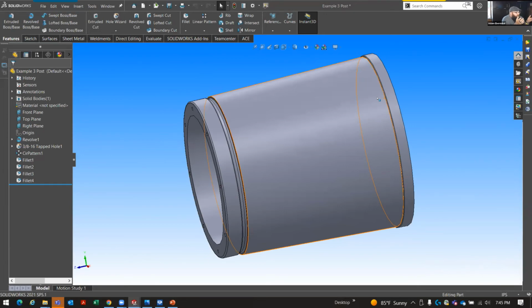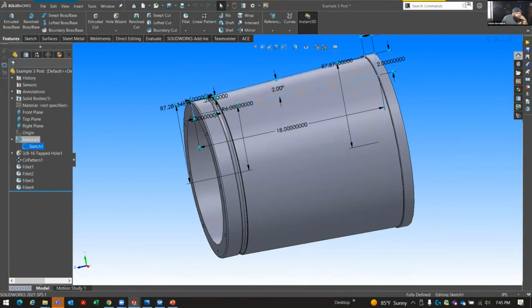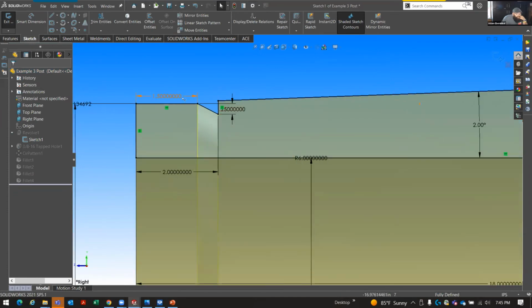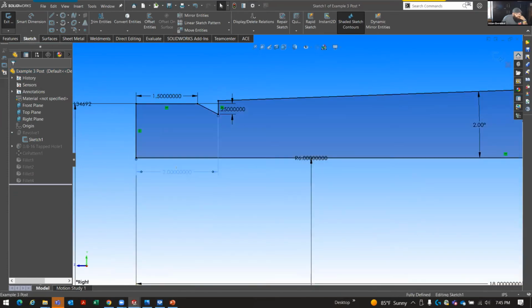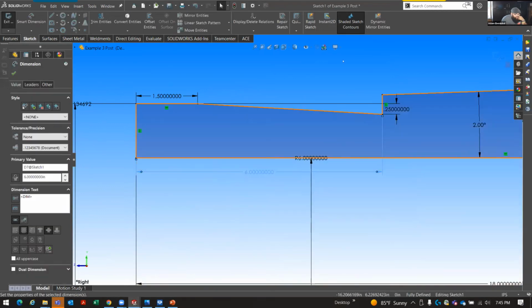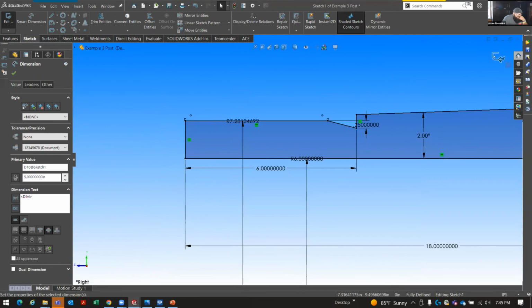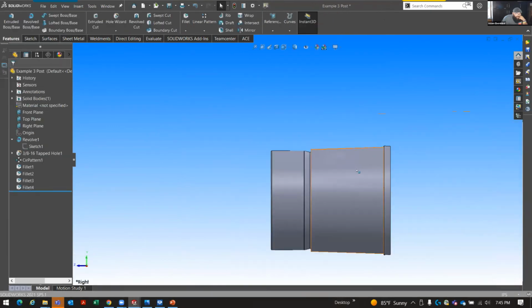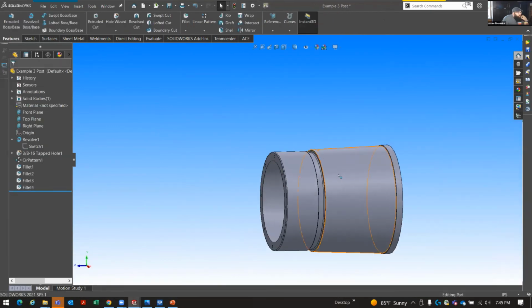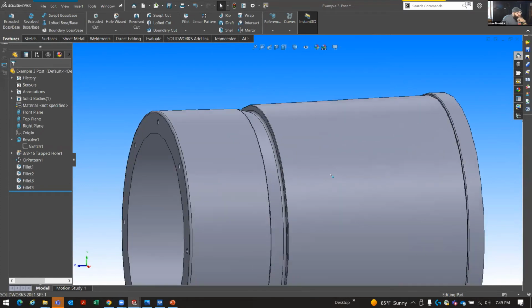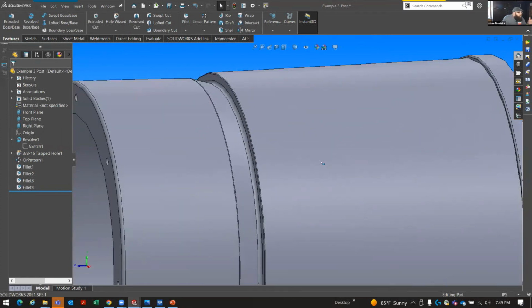Yes, which is only about 3-4 inches, right? Yeah, in theory. So I could have gone back in and changed this dimension here to, I don't know, 6 inches, and tapered much less of it, or even more, or even less, and just had this extra stuff hogged out and rough machined, right?